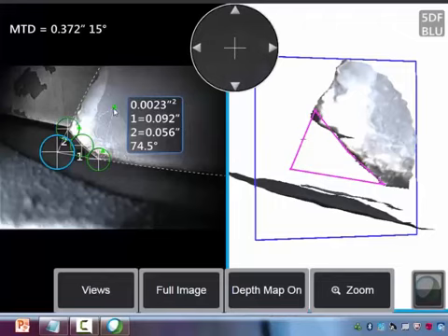Now, when you use this combination of a measurement plane with an area measurement in this way, the software actually adds these lines in the 2D image that extend along the edges of the blade. So this helps us more accurately position this corner cursor so that we're well lined up with the original location of that missing corner.